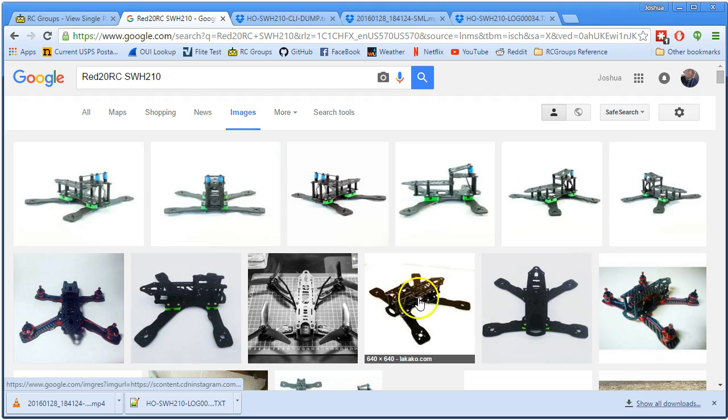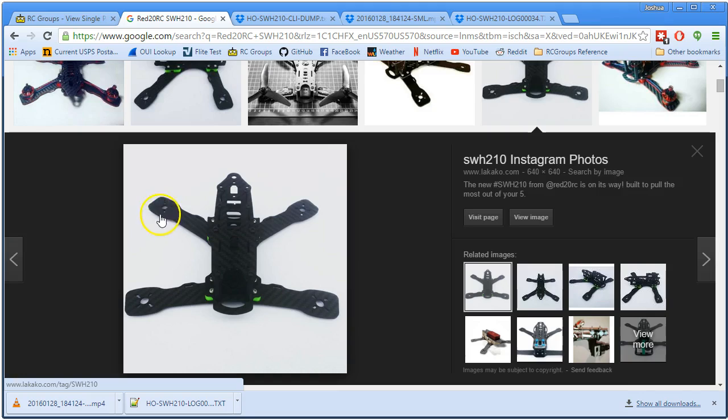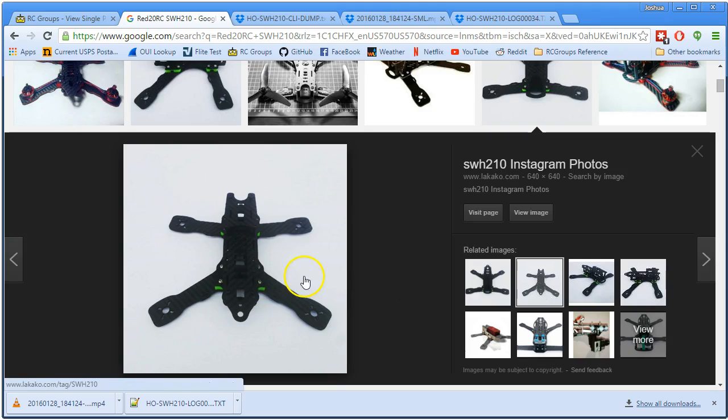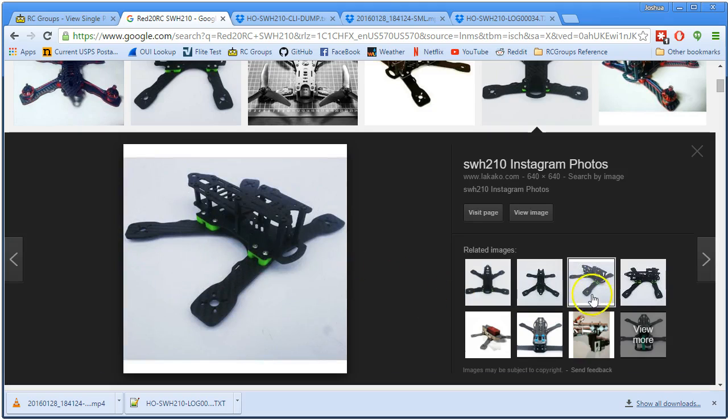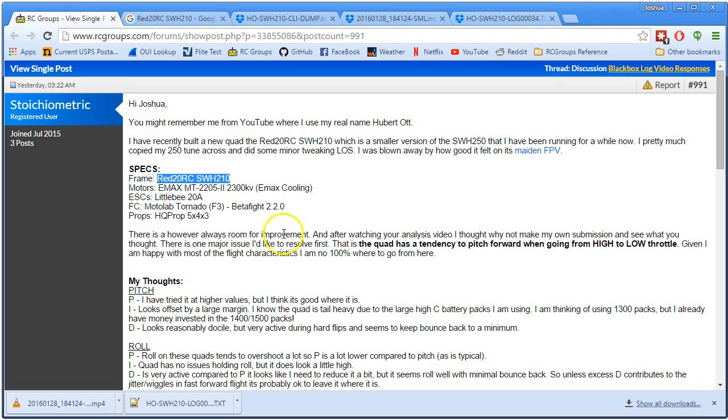Little bit of a weird motor layout. I don't think that should be affecting you too much. I can't tell from the photos whether the motors are square or whether the rear motors are closer in. I think it's just an effect of the photo. Maybe the rear motors are a little further in, and that's having some effect. I would expect that to create roll to yaw coupling. In other words, when you roll, you also get yaw. But I wouldn't expect that to affect pitch at all.